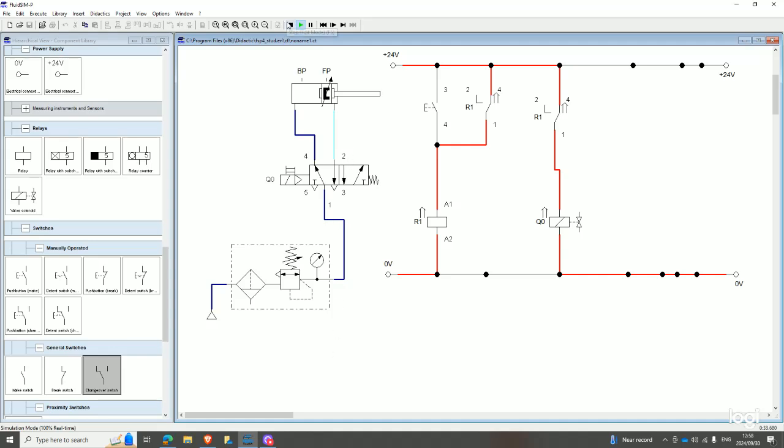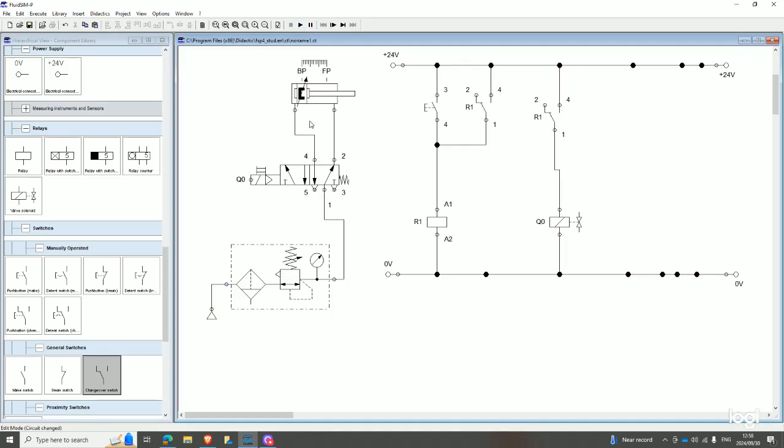So now we need to install an S2 push button that's gonna retract the cylinder, but it's not gonna disturb the functioning of the circuit. So we need a push button that we're gonna connect here. This is how you connect a dominant breaking signal. It's gonna be here, and then it's gonna be connected to here. So if you'll notice, I've used a break push button.